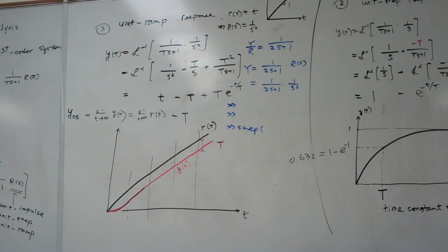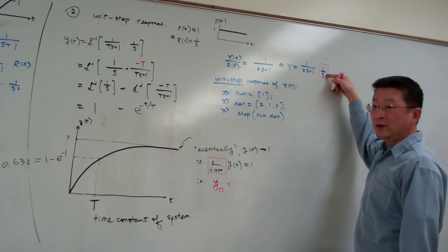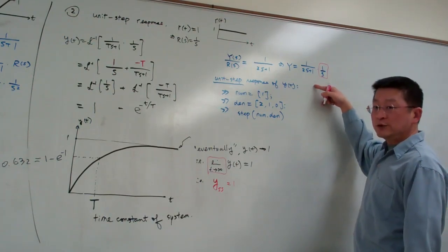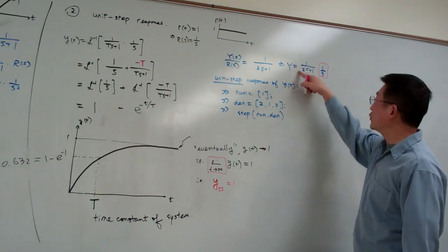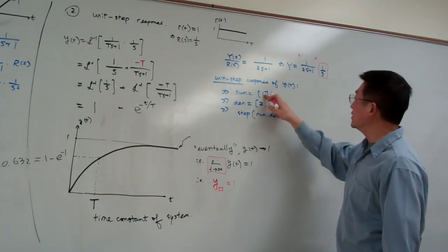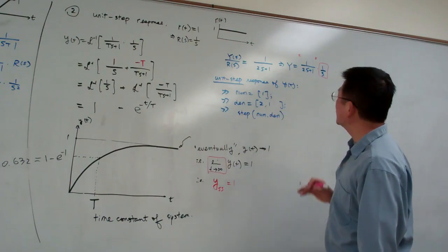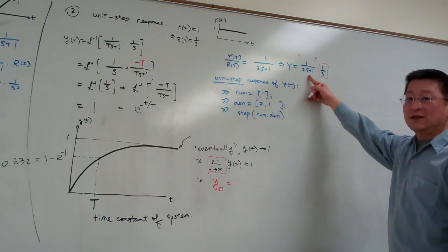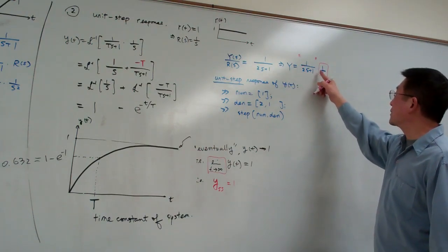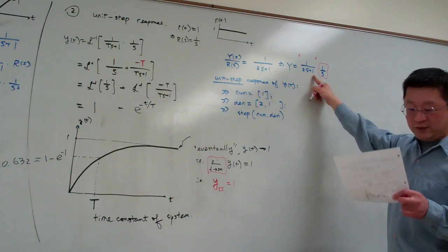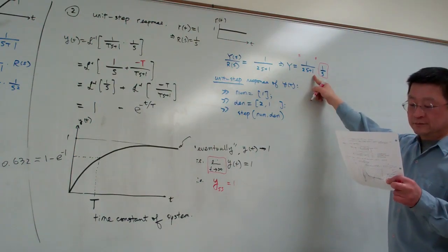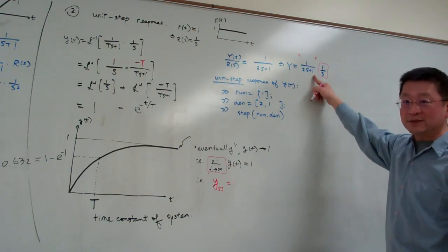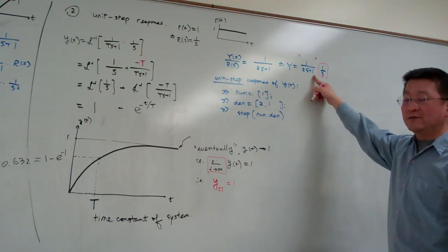Okay, so for the unit step input, I think we stop here. And this is a step input. Basically, this is the Laplace transform of the unit step input. So the numerator and denominator are only this portion here. Okay, so here is 1, and here I need to modify this to [2, 1]. We only input the system, the term that multiplies with 1 over s. We only input this system. You good? Sorry, that's my mistake, I haven't used this for a long time.